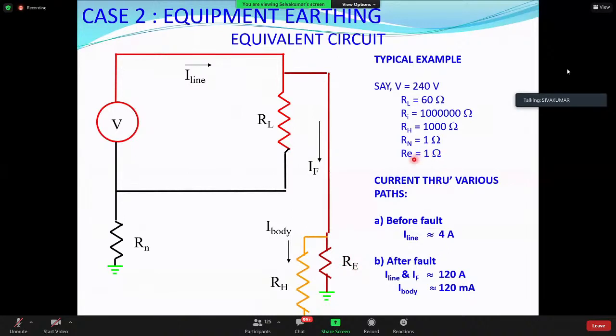But you know how well Indian industries are maintaining earthing systems. It is generally maintained only days before the electrical inspector arrives. So for this system to work, the maintenance of the low resistance earthing is very, very important. This is also not practiced, because the electrical person is not maintaining the earthing system. Even a non-electrical person touching the motor enclosure, coming in contact with the motor enclosure, can get electrocuted. So this is again not recommended in India, at least.